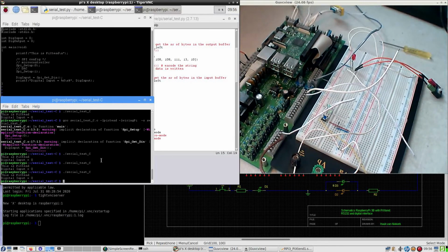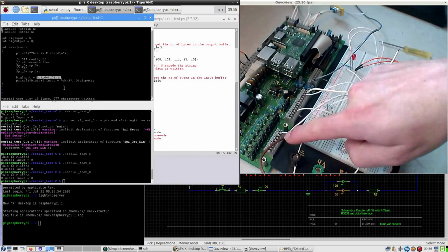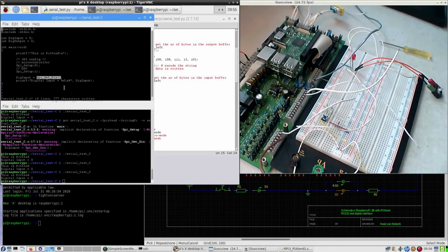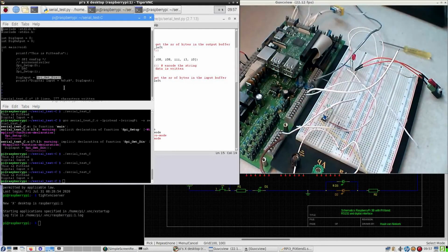It gets a little interesting now, because in the manual it says that this function returns the value of the digital input when it's 1. If all inputs are 1, it returns the number 255, which is correct, because it starts at 0 to 7, 2 to the power 0 plus 2 to the power 1, etc., until 2 to the power 7, all accumulated returns 255.